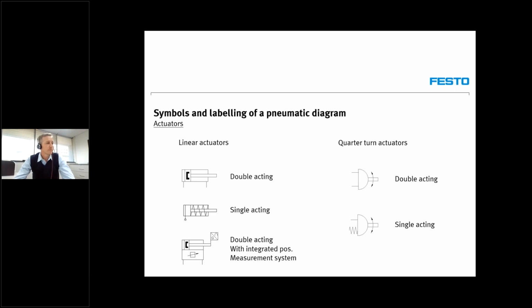Just scanning through questions here. Here's another question. What is the time frequency for your oil drip feed? So I'm assuming he's referring to the lubricator oil drip feed. Yeah. The time frequency also depends on what the consumption of your air is. You need to see that there's not an accumulation of oil in your exhausts or in your silencers. As soon as there's an accumulation in your silencers, you will know that your drip rate is too high. But you can also open up your actuators and see if it is lubricated. As soon as it's lubricated, you will know that the frequency is sufficient.